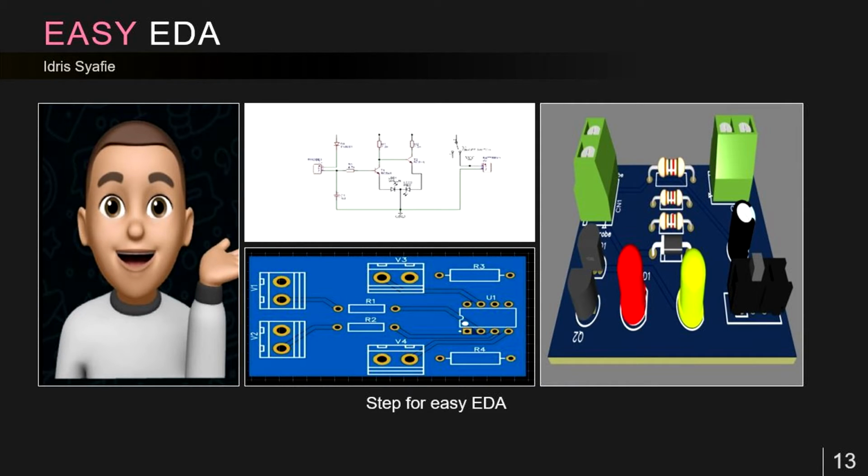After the auto routing is done, create the ground plane on the top layer and the bottom layer. Insert the unavailable 3D models using the 3D model manager. After that, we can show the PCB in 2D and 3D.